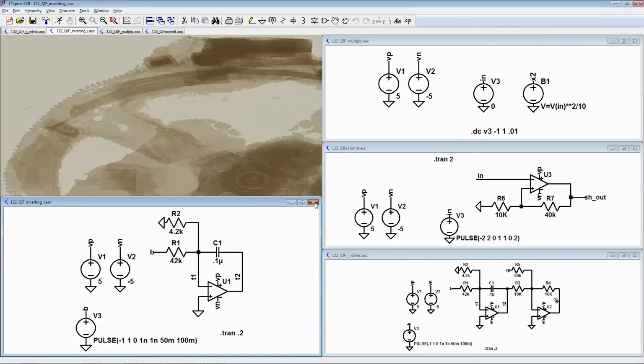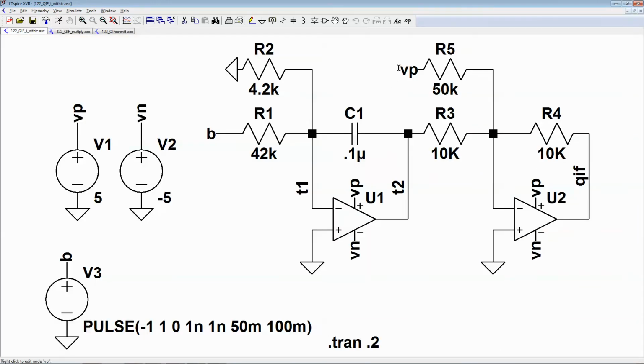Now, once you do that, you want to add your initial condition or your V reset. In this case, I wanted it to be -1, so I add another inverting amplifier with a gain of 1. So now my integrator is non-inverting, and then I add a -1 by putting the power supply into a gain stage with a -1/5 gain, which will give me a -1.